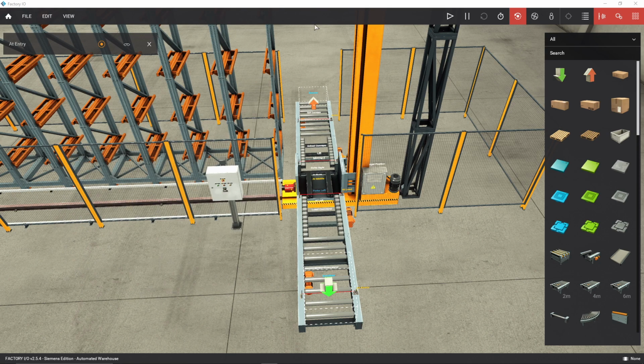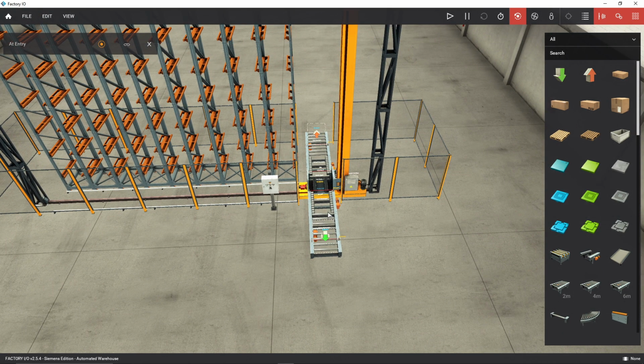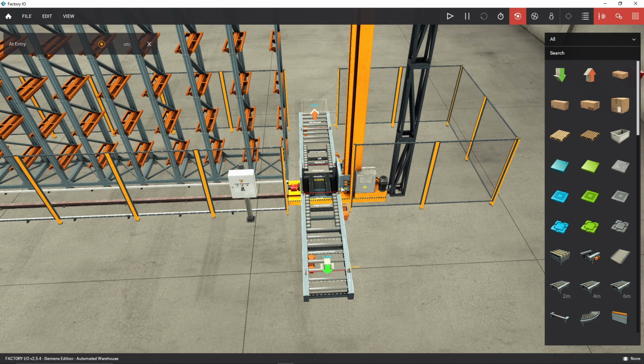Alright, here's gonna be a short video on how to configure your PLC-SIM, TIA Portal, and Factory I/O all correctly. So you should hopefully be able to connect with a simulated PLC to your simulated scene. This particular one that I've picked is one of the ready scenes. It doesn't matter really because I just wanted to see if I'm able to trigger any of the output signals or read the input signals from the scene on my simulated PLC.